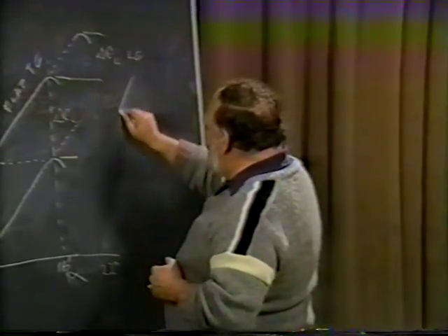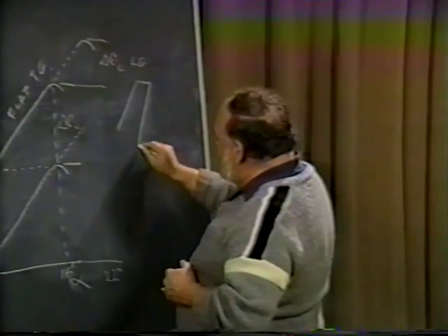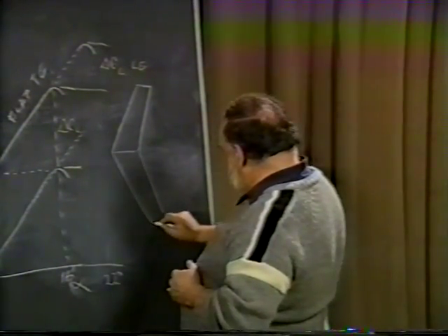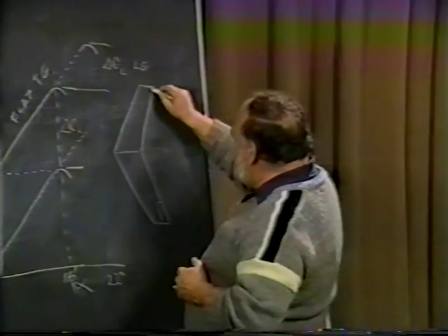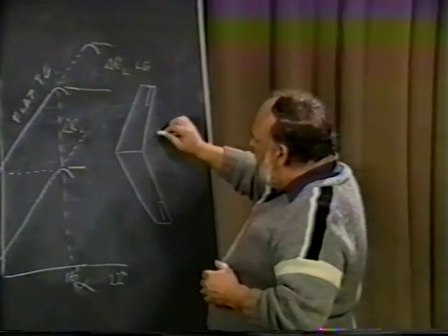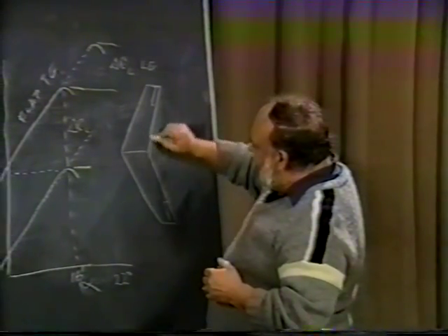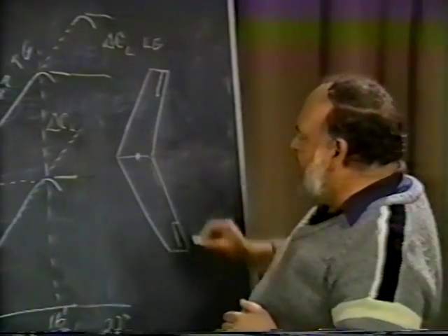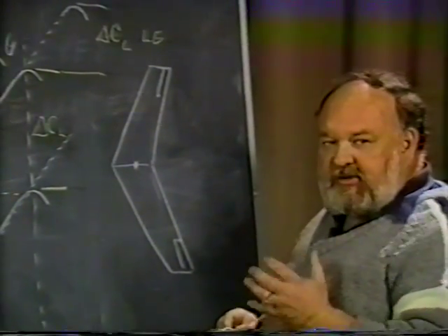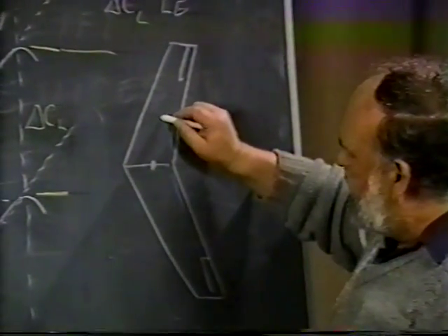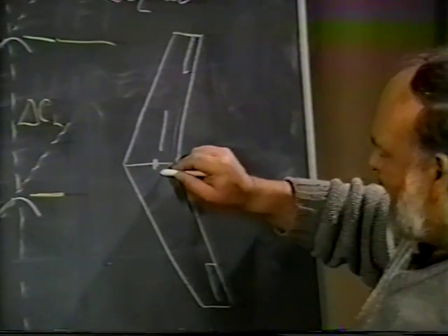Let's draw the flying wing from a top view. It was swept back, with the outboard sections here becoming ailerons and roll control. And they used the flaps in this inboard region here, and it was somewhat forward already, with the center of gravity probably being located here. But they took the split flaps, because it's the one that has the least amount of pitching moment, and they moved it somewhat forward on the bottom of the wing.